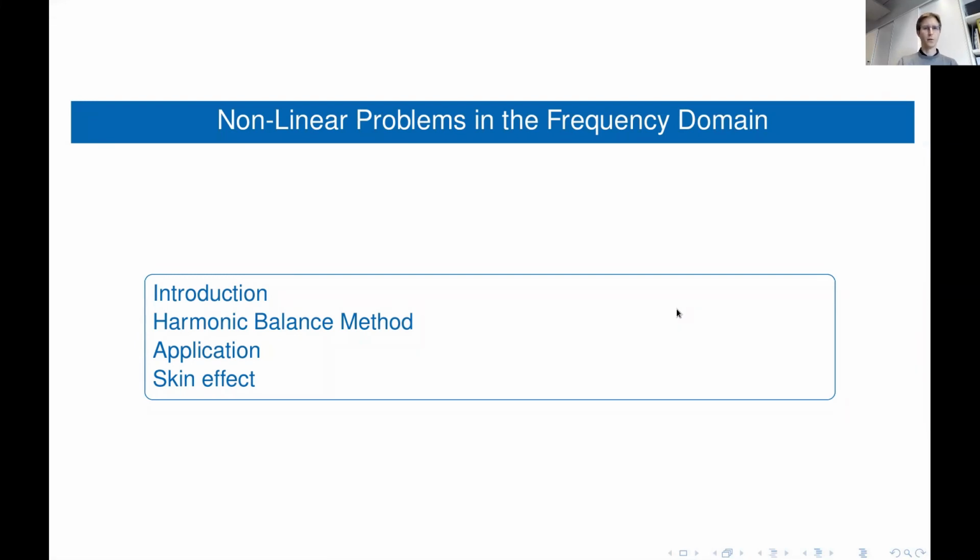Today's topic is nonlinear problems in the frequency domain. After a short introduction, we'll look into the harmonic balance method and see how this is related to the finite element method. So we'll do harmonic balance FEM. And then we will see an application example in computational electromagnetics, solving the eddy current problem, a nonlinear eddy current problem, directly in the frequency domain.